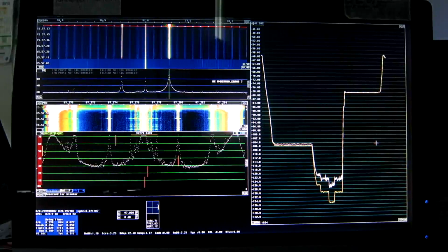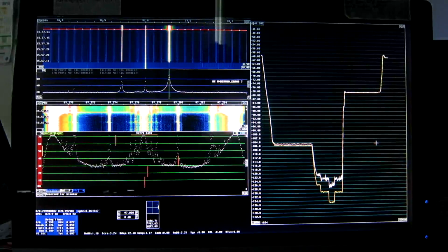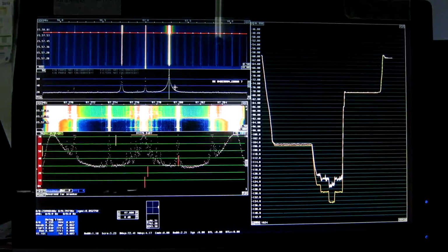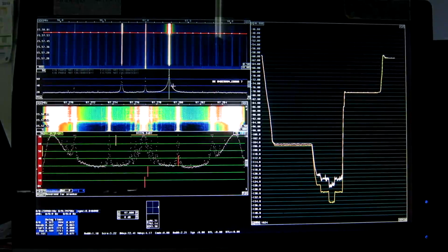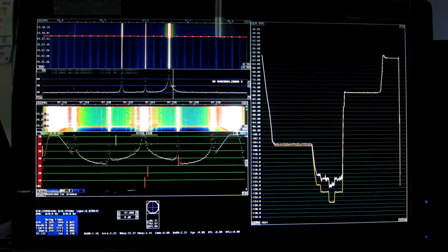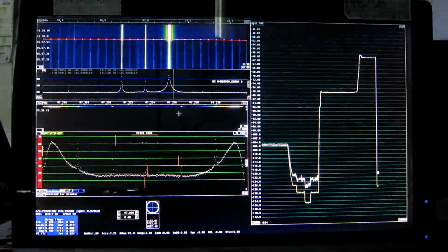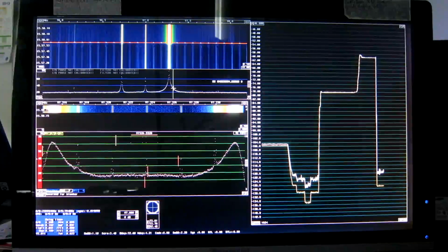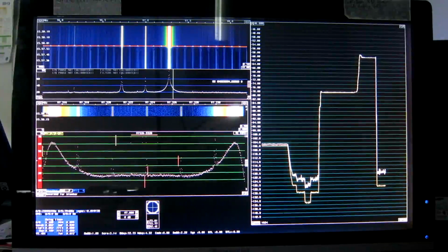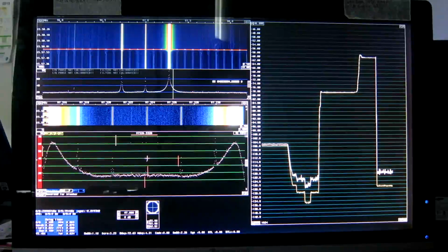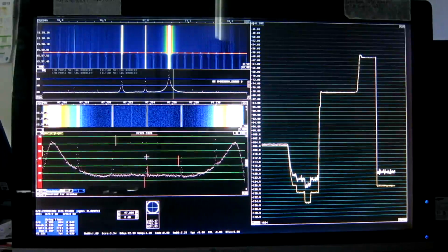Okay, about the resampling spurs, they arise because if I click somewhere where the signal on the main spectrum is still fairly strong, I click here, then we have these spurs at a level that corresponds to the level here, and you can see we have them at a separation that corresponds to the FFT1 bandwidth.